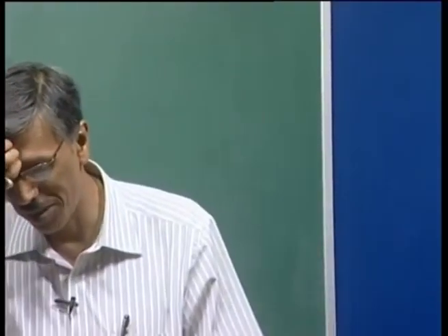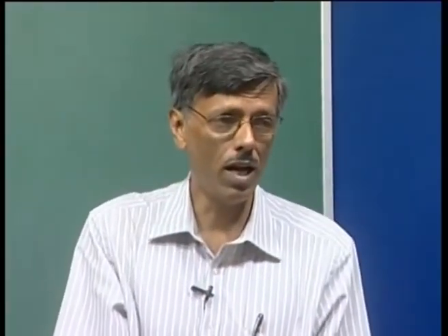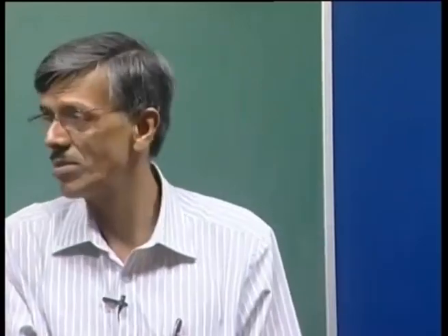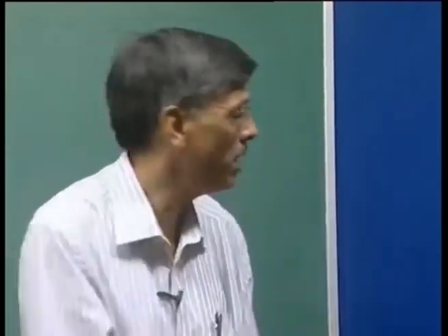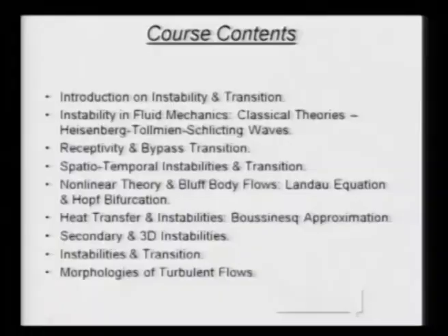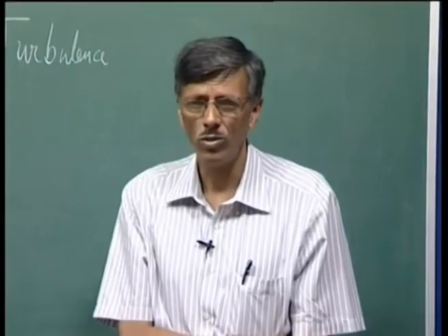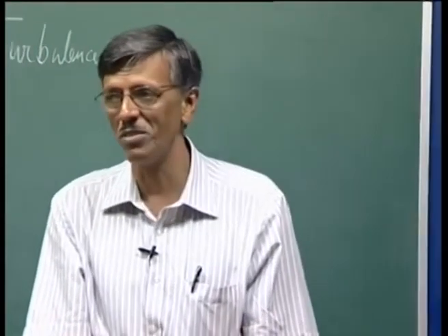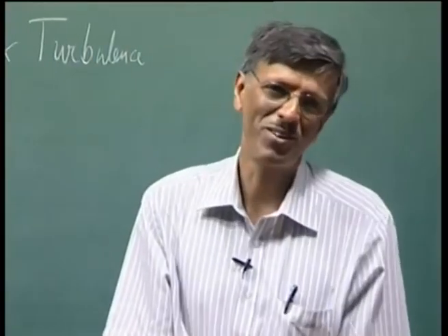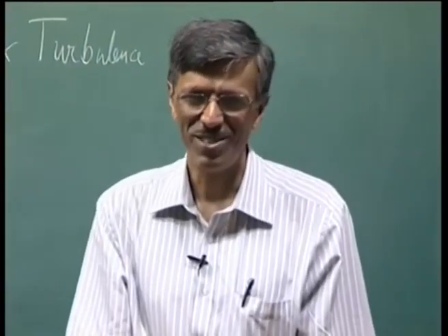They worked on it, and what they found is that the flow becomes unstable, and then you also see some waves. This is what we mean by Tollmien-Schlichting waves, which we have written there. We will be spending quite a bit of time talking about that. What is important to realize is that those theoretical predictions of instability theories were not to be seen in experiment.